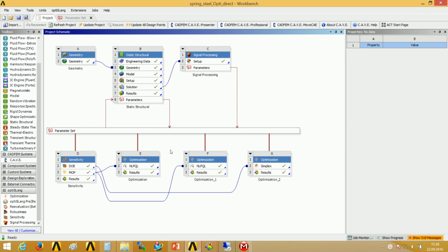And so you can decide whether to stop after this optimization on MOP using these vectors. It means you have 100 design points for the sensitivity, and then the optimization on this MOP with only one validated design. So you have in sum 101 designs. And if you maybe have more time, you can say, okay, I want some direct optimization like the simplex.